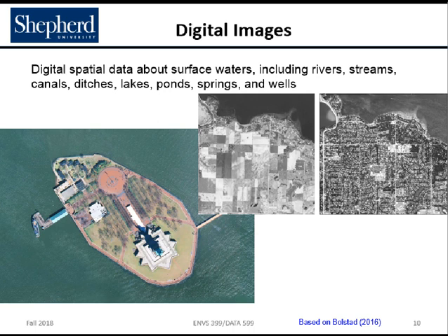Orthophotographs are created by using projection geometry and measurements to remove tilt, terrain, and perspective distortion from aerial photographs. Because they are orthophotographs, object base locations have been corrected for tilt and terrain distortion at ground height. Towers, buildings, bridges, and other tall objects often appear to tilt, as these structure heights above ground are not corrected on the images.